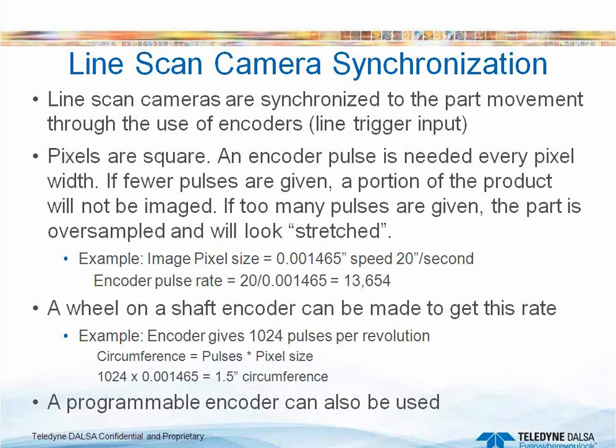In the latest years, nowadays, there are so many programmable encoders out there that you could basically program the encoder to give you the number of pulses you desire per revolution. So that makes things a lot simpler.